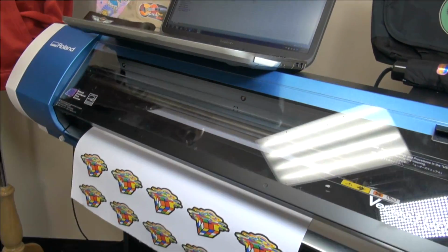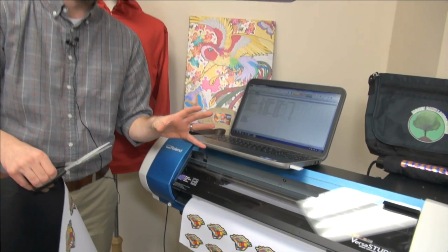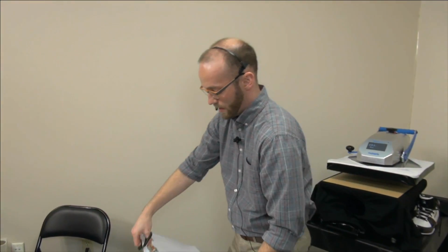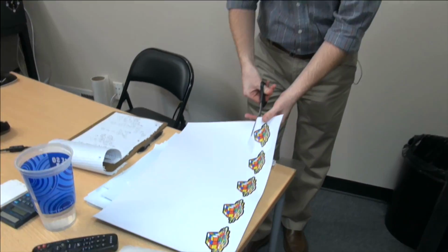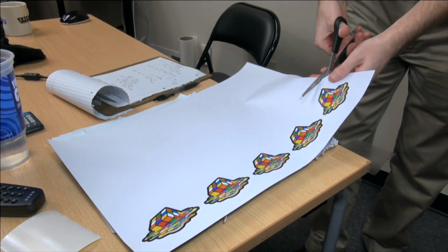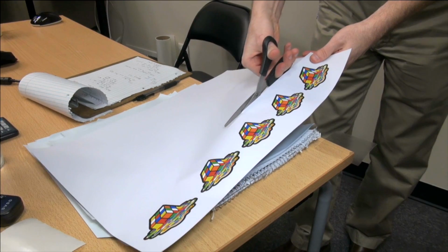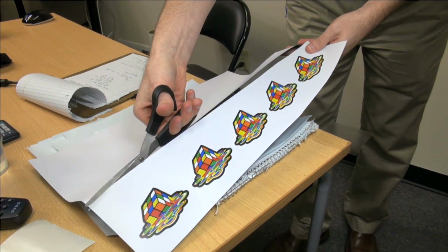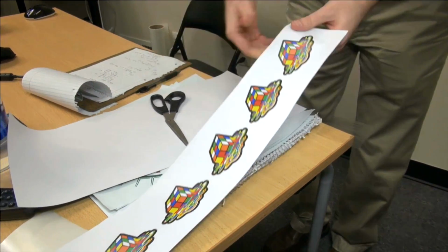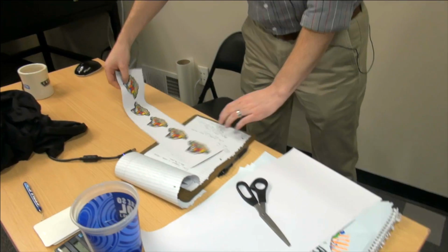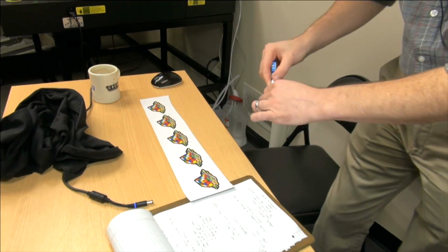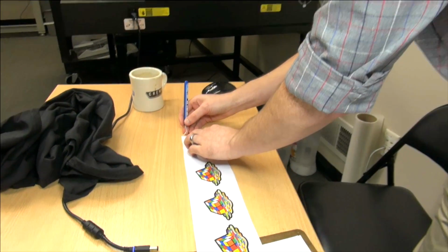But basically, we've printed. The machine has come back and contour cut around the graphic because we showed you the cut line in the software, so it cut where we said. And I'm just going to cut this down into a more manageable piece to do what we call weeding. Since a lot of the room already owns a print cut machine or a vinyl cutter, you're probably familiar with this process. Grab our STAHLS TV weeder. I'm going to pick up an edge.